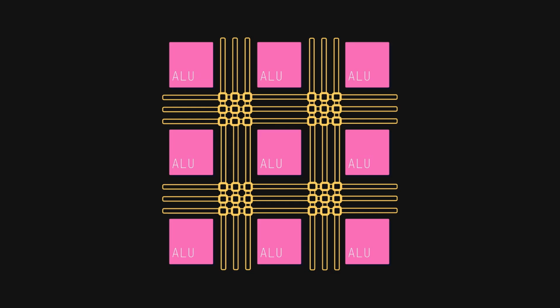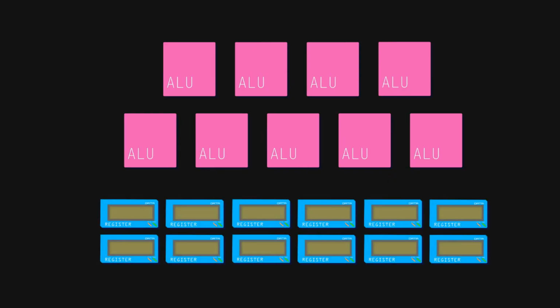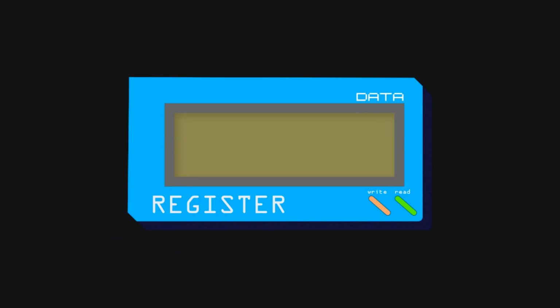A CGRA, as was said before, is a matrix of ALUs interspersed with buses. First, I'm going to do something that is not related to adding control, which is to change these bus connections to something a bit more reasonable. Instead, I'm going to use a register bank. A register bank is just a bunch of registers. If you don't know what a register is, it's just a small circuit that stores data. Usually a word, which in this case means 32 bits.